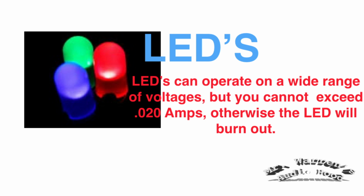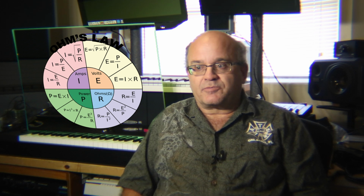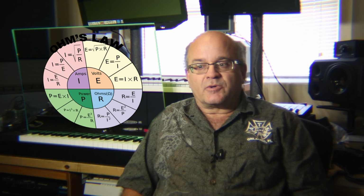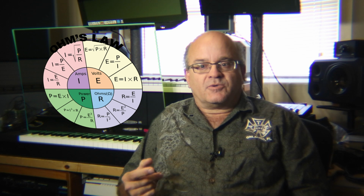They're everywhere. LEDs, light-emitting diodes, are referred to as current or constant current devices. That means regardless of the voltage present, the LED can only draw so much current. This is where resistance comes in, to regulate the current draw to the LED.